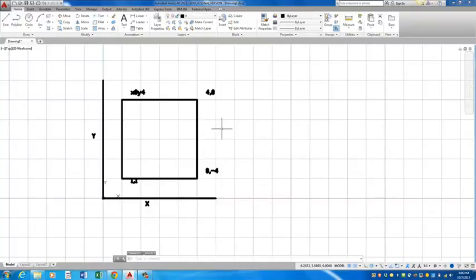So I bet you're confused now because I said we're doing everything in the positive plane before. But if you think about it, relative coordinates are all based off of your current position. So if we are here, we want to go to this point here, we actually have to go in the negative direction. Positive direction would be this way or this way. This move would be in the negative direction using relative coordinates.